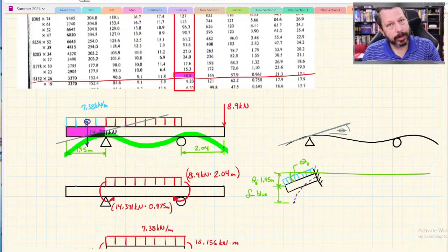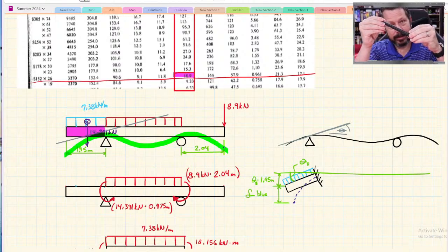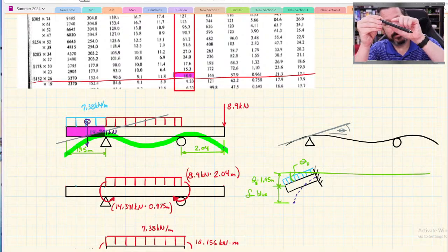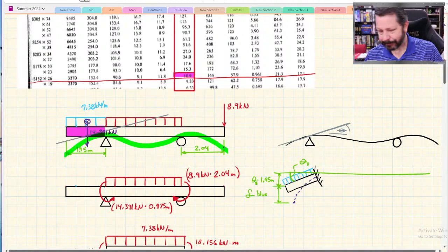So one part of it is just rotating about the pin, and the other thing that we're now thinking of is that it's flexing also. So it's the two pieces to it. And I know it's confusing because, yes, we did include that when we calculated the tilt about the pin, and that would just be this far. But this part of the beam is not straight. It's tilted and flexed. So it's both of those added together.